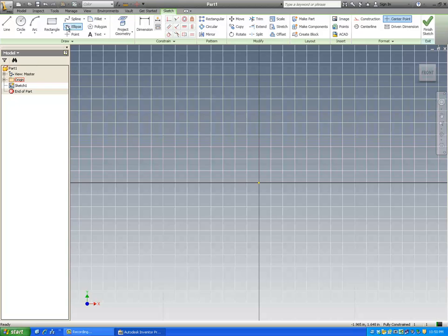We're going to mainly be in either a model tab or a sketch tab in this tutorial. Okay, so I have all these different little palettes up here, so I can draw lines, circles, arcs. You can fiddle around with this. I'll just demonstrate this quickly. So I'm going to draw a rectangle. That's important when you start any drawing entity, that you constrain it with that green snap dot right there to the origin. So I'm going to click there, and then I'm going to drag out and make my rectangle.